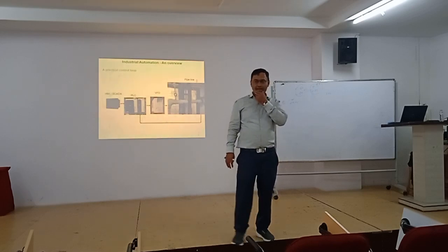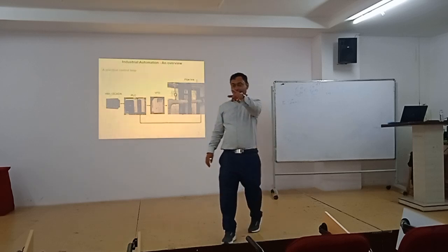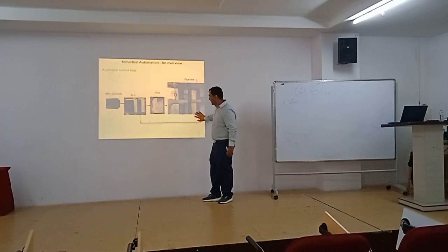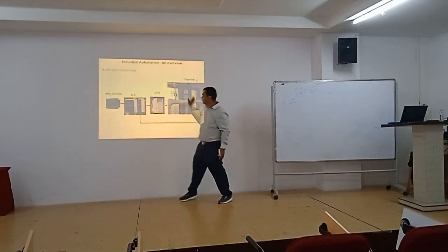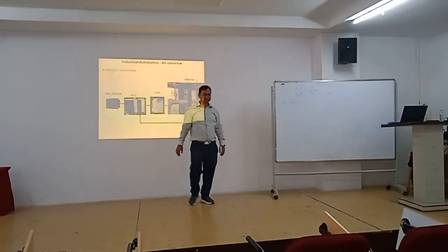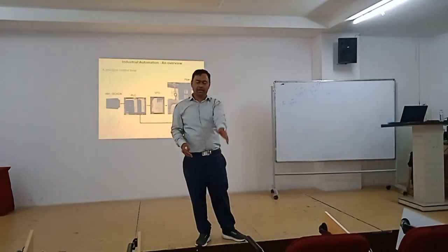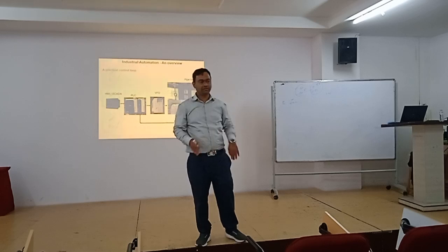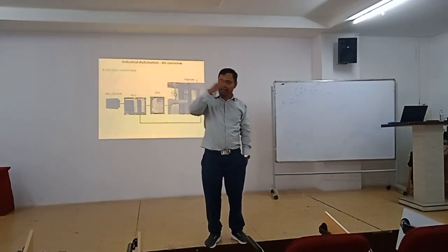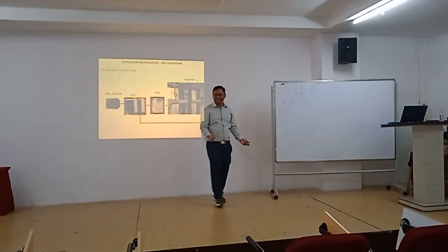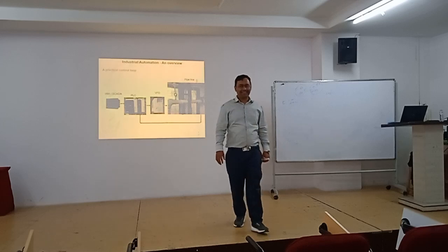We are sensing the speed via encoder. Yes. In that case, what we need to do? Do the same setup, but instead of measuring the flow, you need to measure the speed, and you have some different program. Or maybe all four programs will be together only, but at one point only one will work. And that speed will again be achieved by the VFD only. Correct?